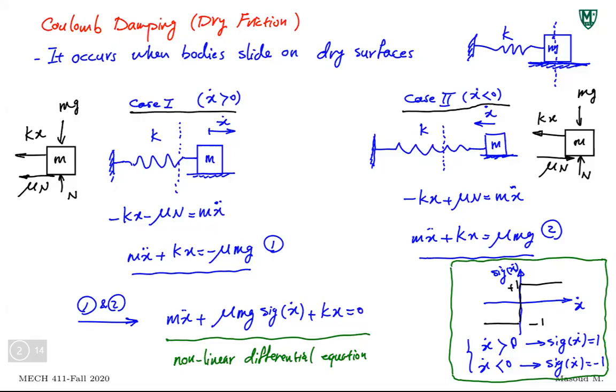They solve these equations one by one for different phases of the motion. The first phase is when the velocity is positive, or actually we're going to start from the end, when the velocity is negative. And then when the velocity is positive, we solve it again for the next phase. So we are going to solve this for different half cycles. Imagine, look at case 2: if this is the mass, the velocity is negative, it comes all the way, passes the equilibrium point, goes from the right side all the way to the left side, and stops there. This is half a cycle.